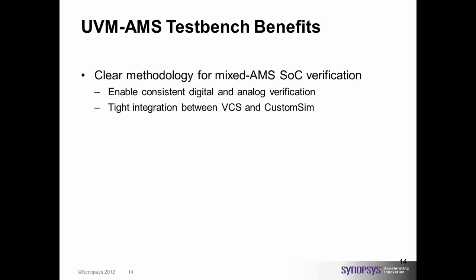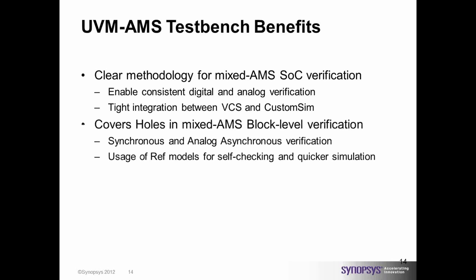Tight integration between VCS and custom sim, so that we can integrate VCS with the custom simulation for the analog components. Cover holes in mixed AMS block level verification, so synchronous and asynchronous analog verification, usage of ref model for self-checking and custom simulation.